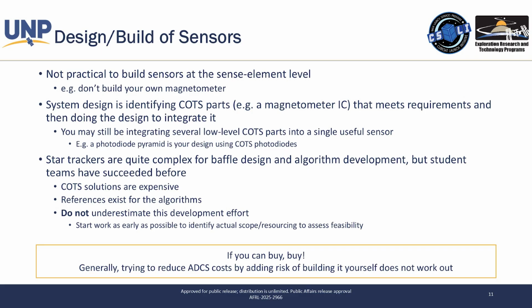Does it ever make sense to use your solar panels as a coarse sun sensor? Yeah, you can. I haven't really seen that too much because mostly what it does is you have to put all that sensing now in line with your power generation. Feels like we just don't do that because it's kind of a complexity issue. It's just easier to stick on a smaller photodiode and just measure that directly and do all your math without also trying to get power off of that. We don't do that a whole lot.